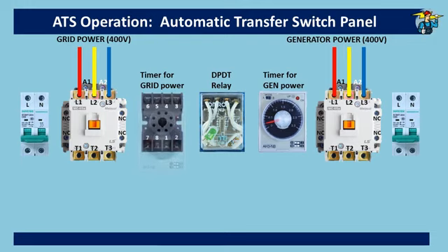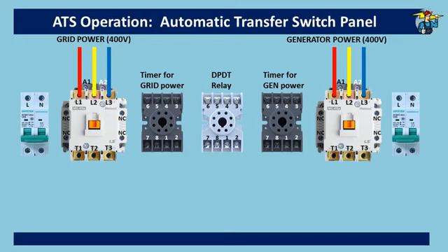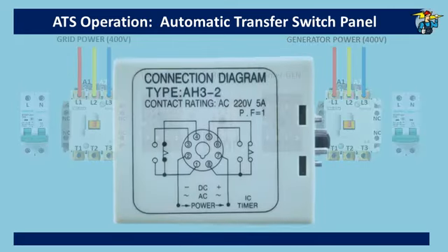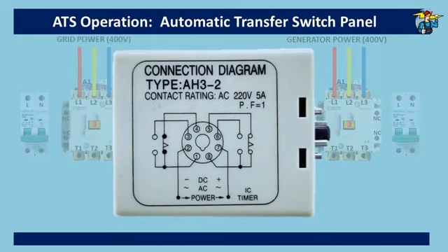When you take timers and relay out of their bases, you will see the numbered ports like this. On this picture you will see how the positions are numbered for the normally open and normally closed positions, and also the common points and the power supply points. Power connection for the relay or timer is to be given through the points 2 and 7 according to the details given on it. AC or DC power will be connected to these points.